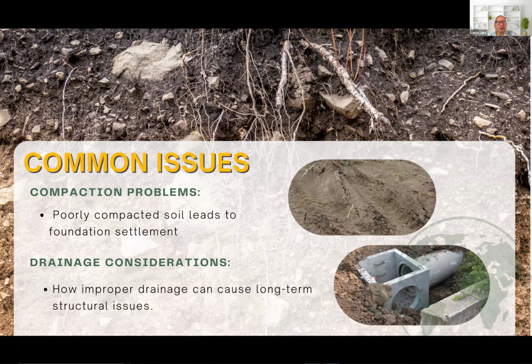And then you have drainage considerations, how improper drainage can cause long-term structural issues. So you have a site that is not draining properly, you have water ponding around against the foundation. That's not a good condition either, right? So, let me see what else I have.